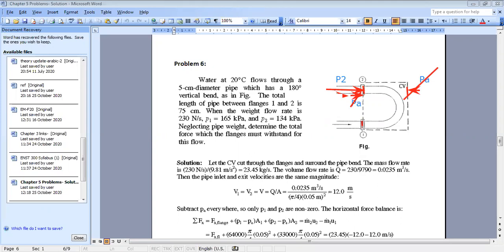While taking the control volume, we can take it even if it has two different materials, here we have air and water. It doesn't matter. Now your control volume, you can take it following the geometry if you want. It's not wrong. It's not necessary to take a rectangle. But here when you consider the control volume, mainly you are considering water, meaning the pipe system with the water inside. This is your system. So for air you neglect, air has a negligible effect. You are taking the control volume, not the air. You are considering the pipe and the water inside.